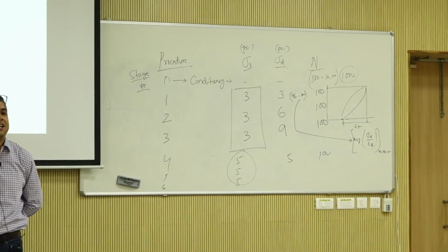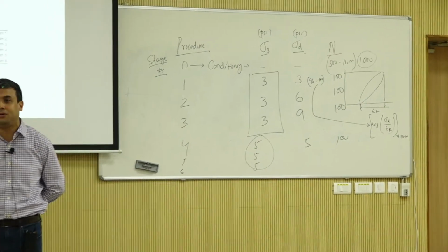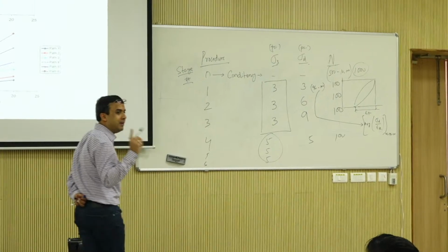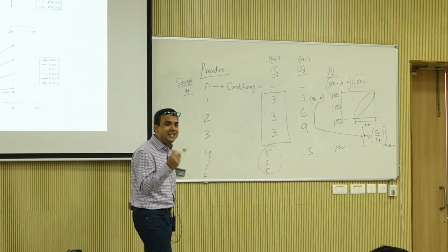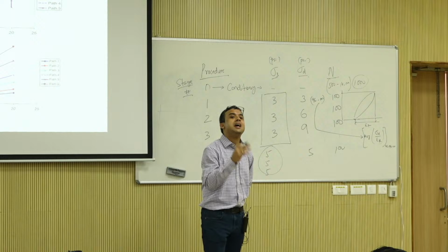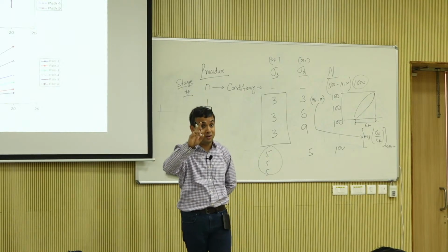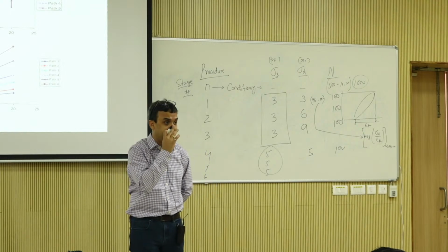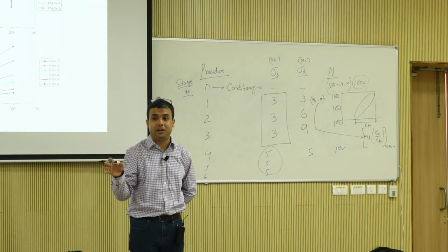That's an elastic representation. That is not resilient modulus. Right? Resilient modulus is not one value. A material cannot have a single resilient modulus. You can take a representative modulus. That's a different thing. We can talk about that tomorrow. Today we'll not have time. I will probably talk about that tomorrow actually.